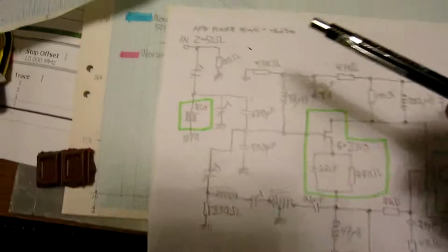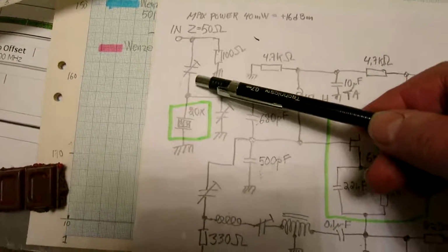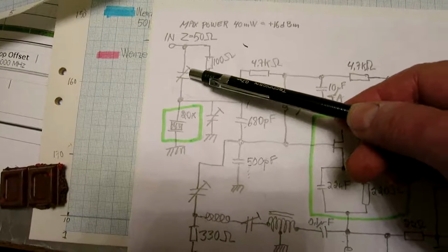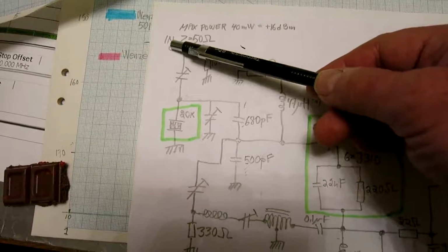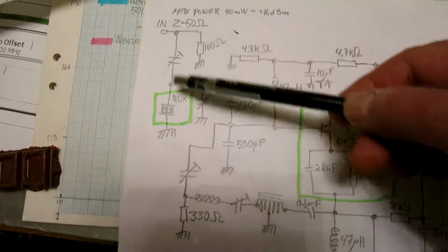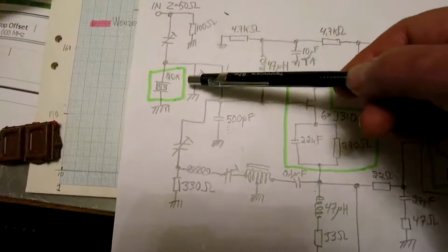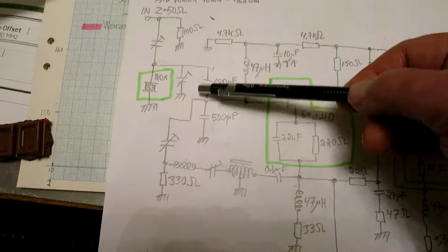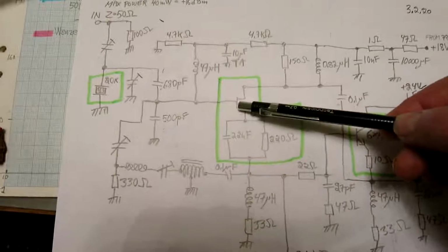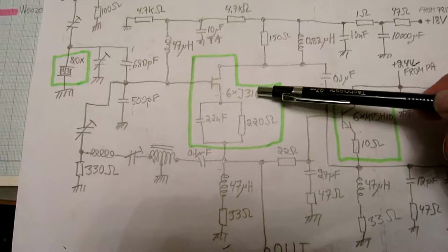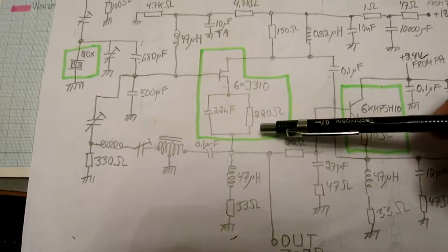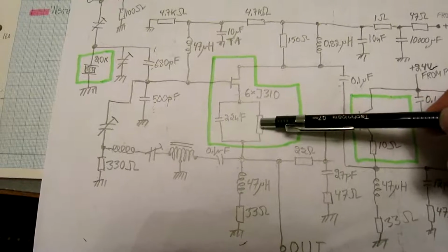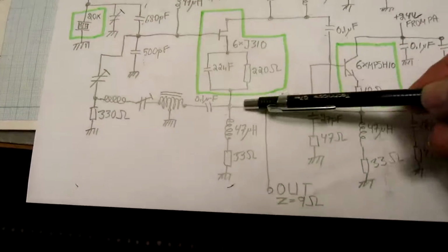Here is the preamplifier. Input here through a capacitor, and there is also a resistor of 100 ohms to ground. This capacitor is tuned for the impedance here to be exactly 50 ohms on the center frequency. 20 crystals in parallel, tuned with this capacitor and also these two for resonance on 10 megahertz. This voltage divider gives a reduced voltage to the gate of 6 parallel J310, and they have all separate resistors in the source, decoupled, to make the current the same through all transistors. And then the output comes here.